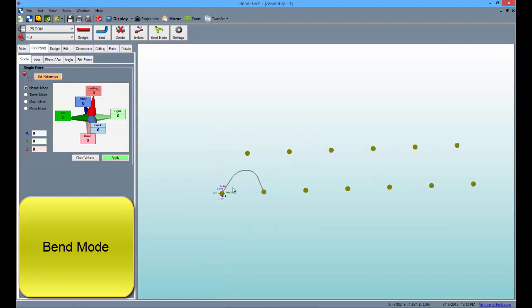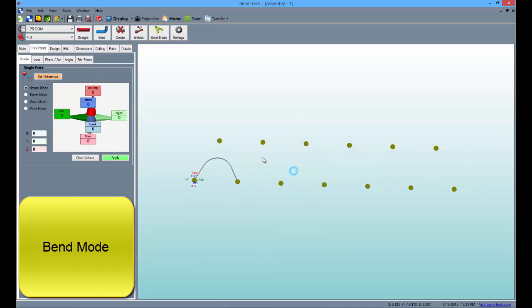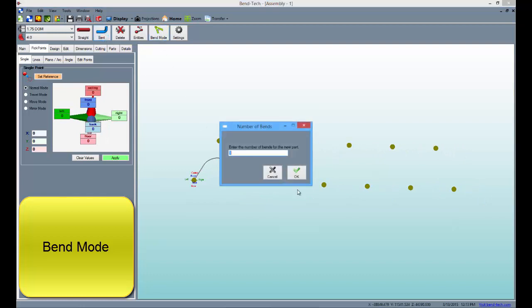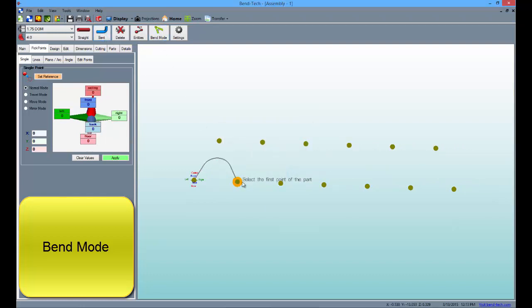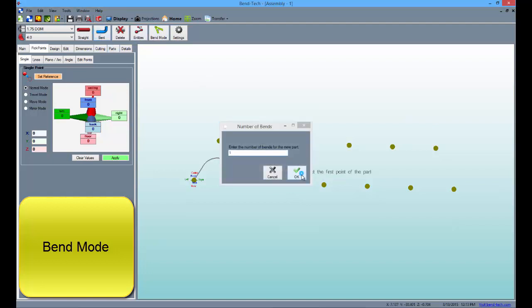When creating a bend, you'll need to click a minimum of 3 pick points. So select the Bend button first, then the first pick point, then the Bend Mode button, then select what kind of bend will be defined, then click the remaining 2 pick points to finish the bend. These next few examples should clear up any confusion you might have about this process.